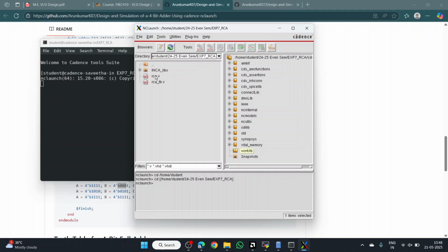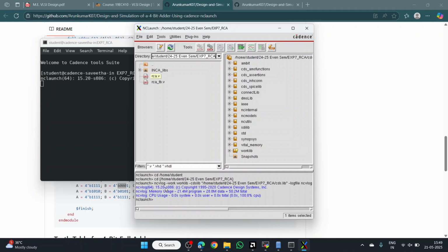Click on your Verilog file, that is the source code, and do compilation. You just look at this. It is launch Verilog compiler. Just click on this, and the console will give you the information. If there is any error in the program, that will be indicated here. Okay. Now I compiled the source file without any errors. Now let me do the compilation of the test bench. So click on the test bench file and do the compilation. Again, this is also working properly without any errors.